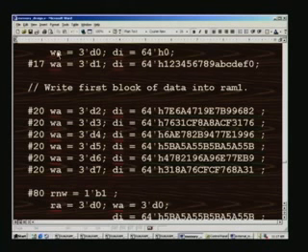And what we are going to do is, first we take one of the RAMs, let us say RAM 1, and RAM 1 is selected, and we are going to write into this RAM 1, right. And so here R and W equal to 0 has pointed to RAM 2, that means that is in read mode, right. But for the very first block of image that you are going to write, there is nothing available in the other RAM, so there is no point in reading that. So we do not have to read concurrently. That is why we are merely writing the data there.